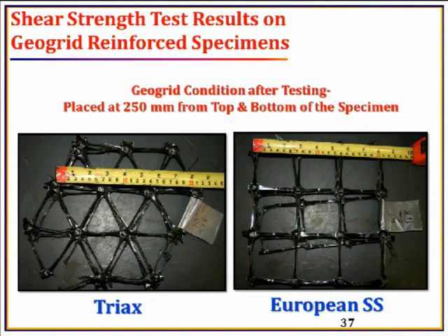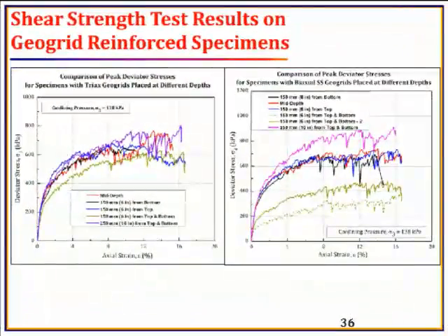One by one, when these Geogrid ribs are being torn apart, I think they are making these shifts in these curves. These jumps were because of the breaking of the membranes and continuous reorientation of the ballast materials that we are experiencing in the whole specimen. So that's maybe the reason we didn't have any smooth curve like in the case of soil that we are expected to see.